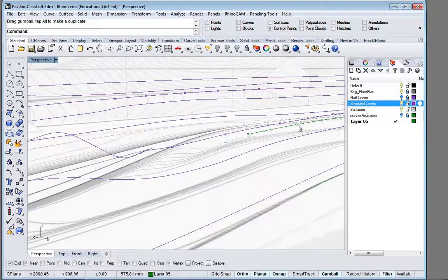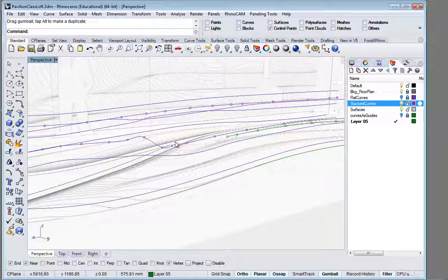That's also why you'll notice that when I went in here and started pushing these things down, I was only doing those curve sections to get us the base shape, and then I didn't really care about that. Those no longer became section curves, because I needed to make them so that I could create that flat plane. So now this curve, as you can see, is now a three-dimensional curve. It's no longer just a planar section curve.